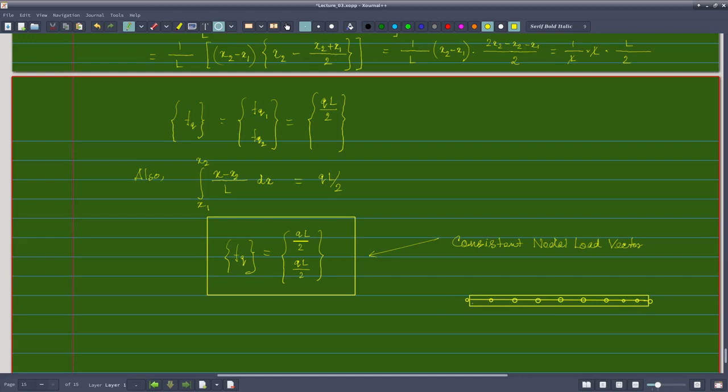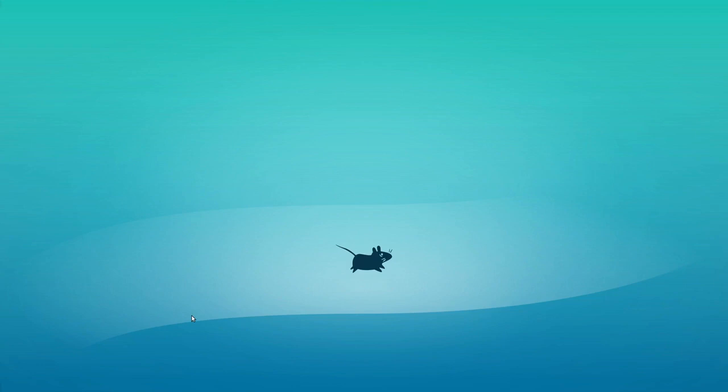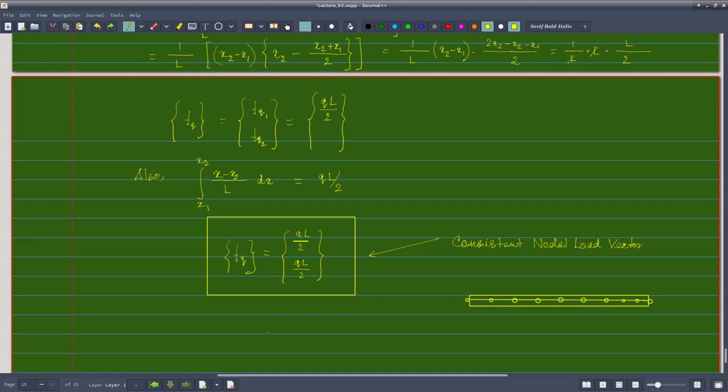Another way is to have a higher order finite element. Suppose instead of a linear finite element, what we had assumed here, my other alternative is to define a higher order element. For our case, what we had assumed, u within the element was a linear function, a0 plus a1x, right? And then by using weighted residual method, we have derived the finite element equation. I can have a three-noded bar element with a quadratic function, say a0 plus a1x plus a2x square.